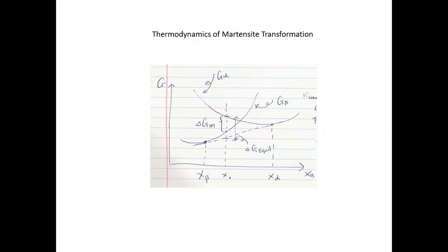for the quenching, the temperature is reduced very, very quickly, right? So you're taking away all the thermal energy from the system, so the atoms have virtually no time to diffuse around. No diffusion really occurs in the quenched system. That's why it has to find another way to lower the free energy.